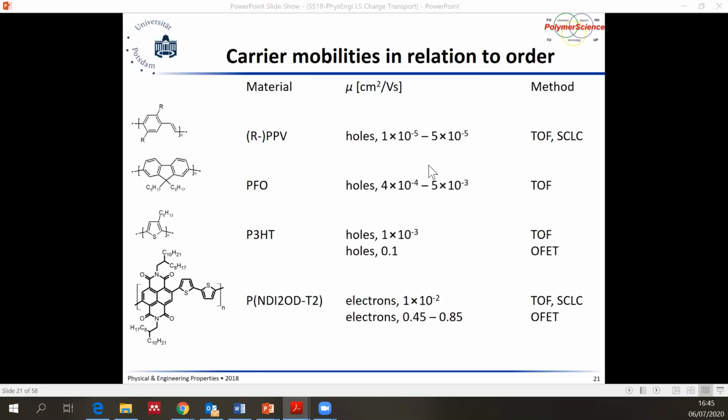Mobility is carrier density dependent. As we said, because we have traps, if we have systems where the carrier density is very, very high, then some of those carriers can fill up the traps, and then essentially other carriers are free to propagate through the active layer, similar to a band-like structure, because now all of the deeper lying traps are filled, so new carriers cannot occupy those states, and as a result we get much higher mobility.